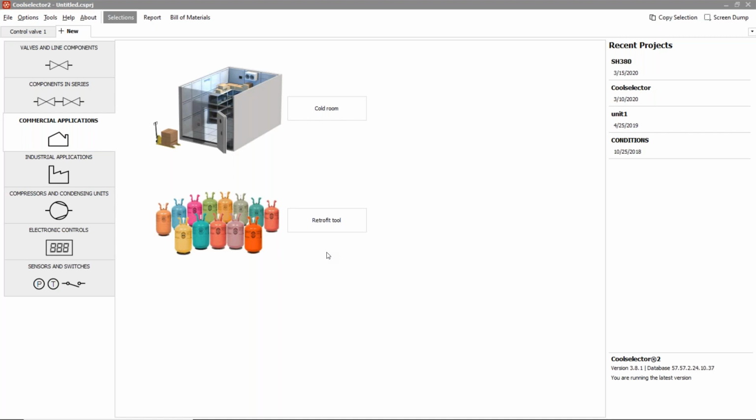You can see all the line components, compressor, piping design, a simplified model of the system, indicating both refrigerants. If you get different results, or it will be okay, then keep the existing line components with the same size, or do I need to consider a different size, like the expansion valve? Basically, it's purely thermodynamic.